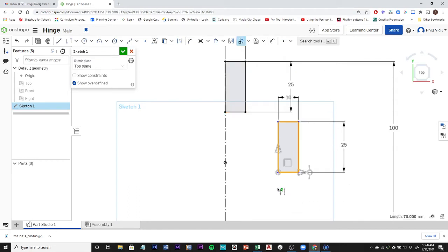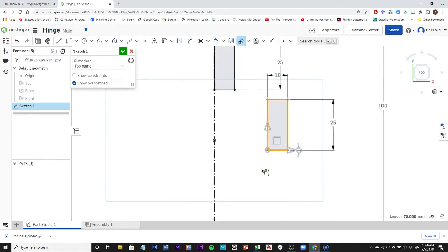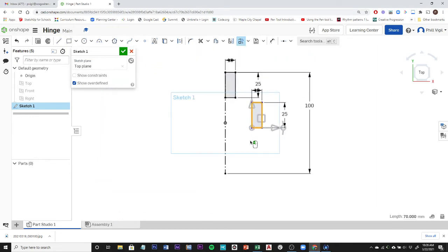It's going to place those things here and also go into what's called transform mode, which is this here. So now I can move my copied items in space where I want them to be. It attaches this snapping point to my object, and I can grab that point and place it anywhere I want to on the object. So let's say I wanted to attach this corner to that point. So I click on that, move it there, then drag this thing over and let it snap to that point.